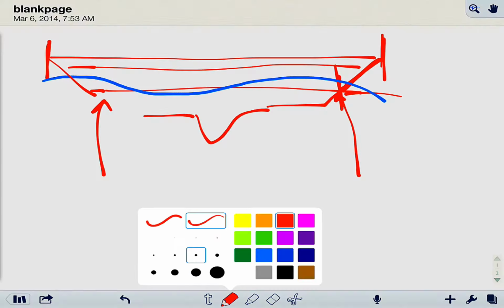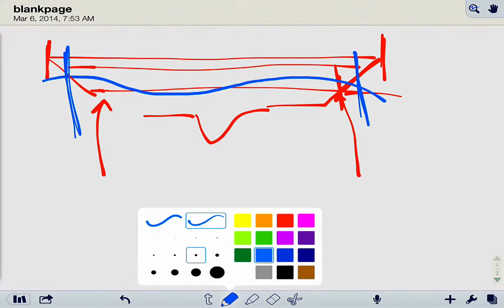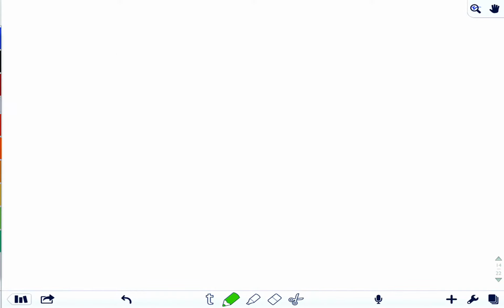So your actual wetted length goes from here to here, so it's longer than the original static wetted length that's sitting at the dock. So you increase the effective length of your boat, which allows your hull speed to be increased. And later rating rules tried to get fancier, and they tried to measure places above the water line as well as at the water line to try to keep you from just simply using long overhangs to make a longer boat than what would be measured for the ratings.